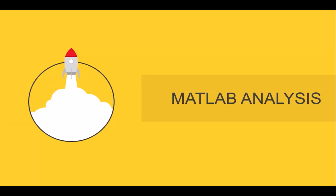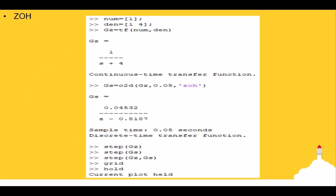Okay, next we move to the MATLAB analysis. Firstly, we generate the zero order hold, which, as we know, is an exact discretization in the time domain for staircase input. So this is the MATLAB work. Firstly, we need to generate the transfer function, which means we need to insert the numerator and denominator. And this is the transfer function, which is 1 over s plus 4.